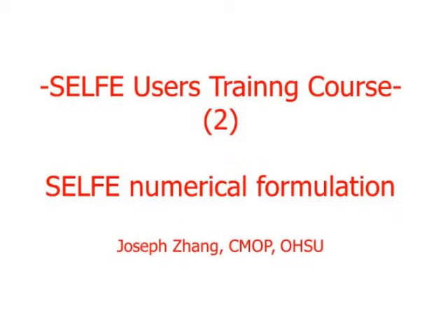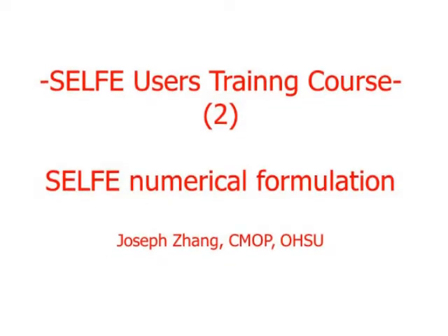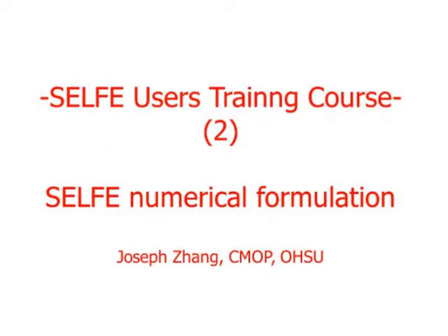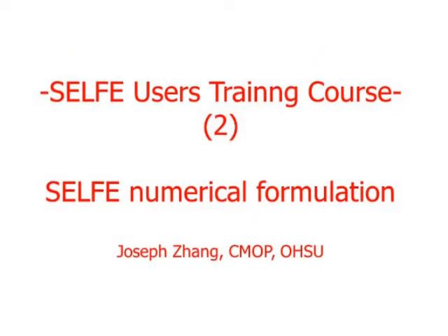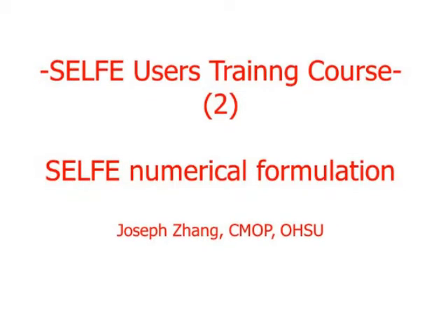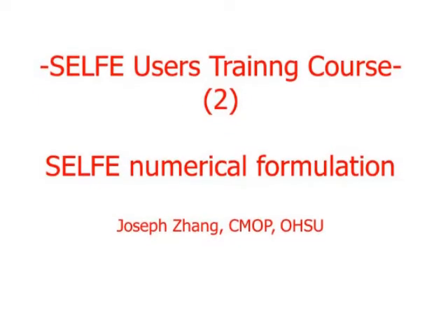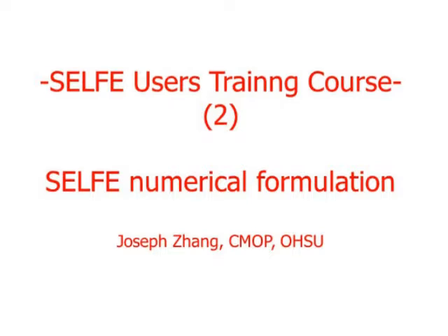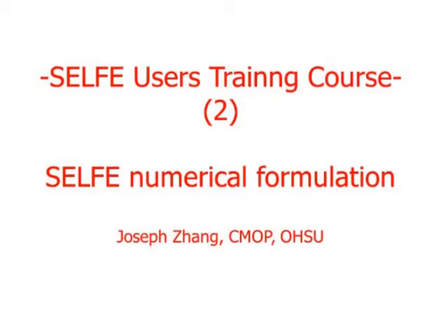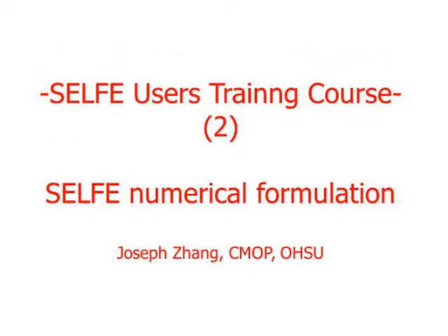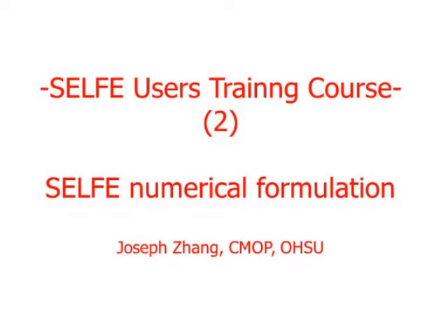And in this case, this stencil actually is not always well formed, in the sense that in some cases, for example, 1, 0 and 2, 0 may be very close to parallel to each other, because that's a degenerate case. So in those degenerate cases, we basically throw the equations out. We have too many equations anyway. So the cutoff angle we used finally is 1 degree. Okay, so if the angle is very close to 179 degrees or larger, then we just throw that equation out.